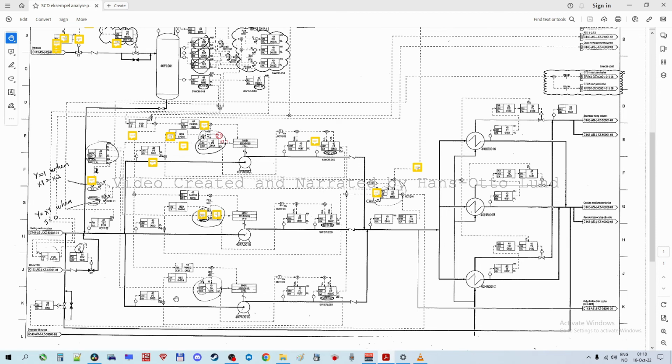But what you need to take care of first is to make sure that the pressure on the inlet of the pump doesn't get too low. So on the inlet here you have a sensor which detects if you get a too low pressure on the line.